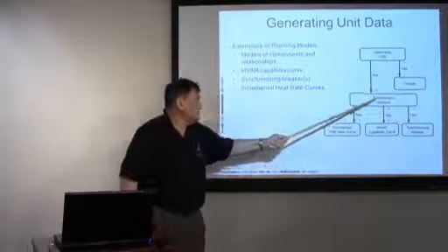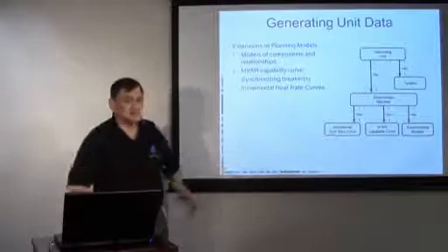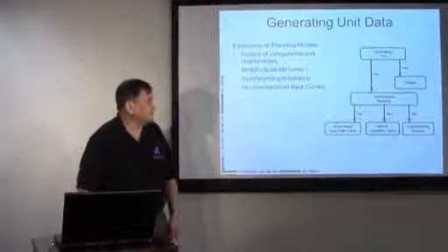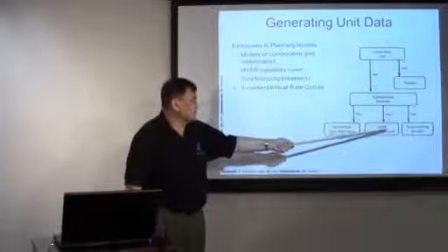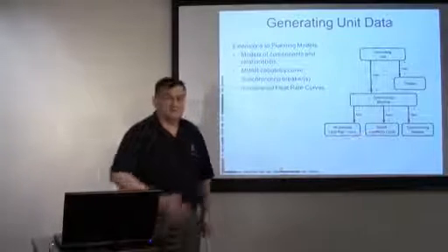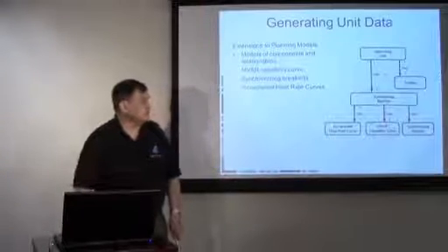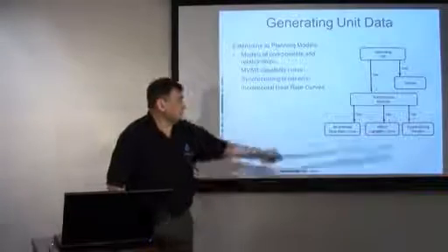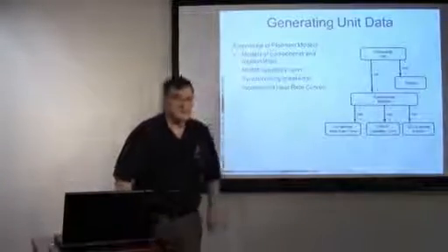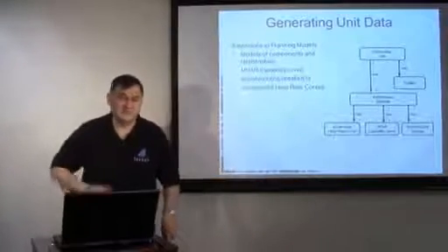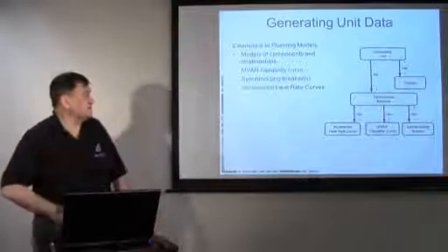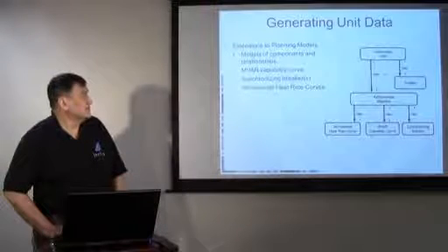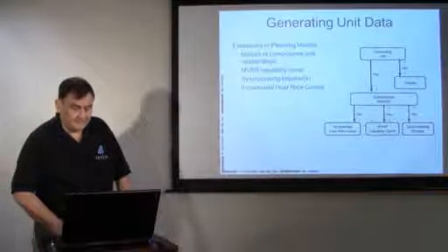That synchronous machine can have heat rate curves that determine its efficiency for where it's dispatched. We talked about the megavar capability curve to determine how much megavars it can produce and absorb depending upon the real power output. And it can have 1 or 2 synchronizing breakers. These are the breakers that will actually synchronize that system. So we do see some more detail there.